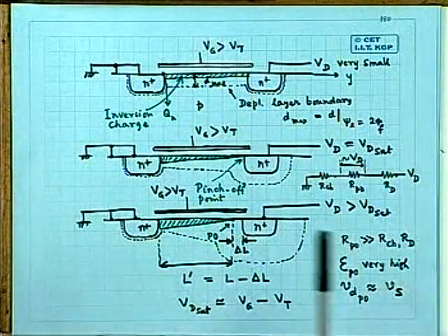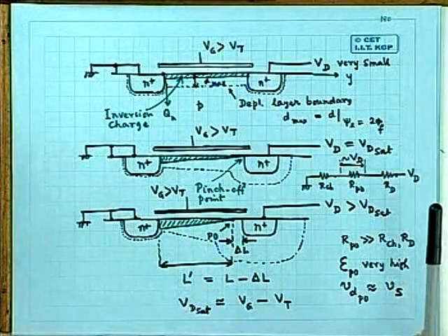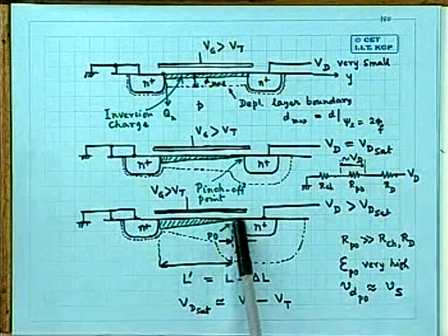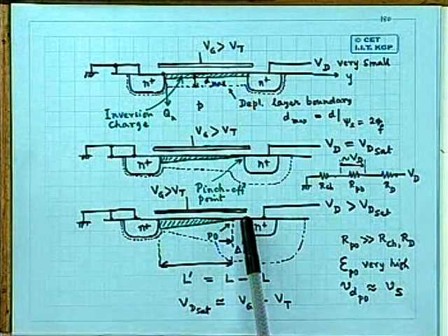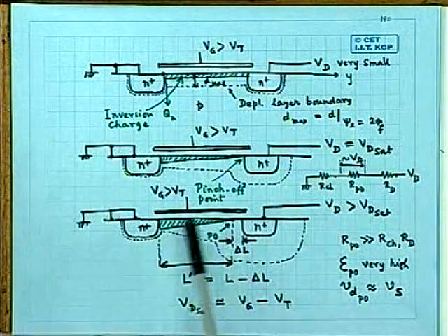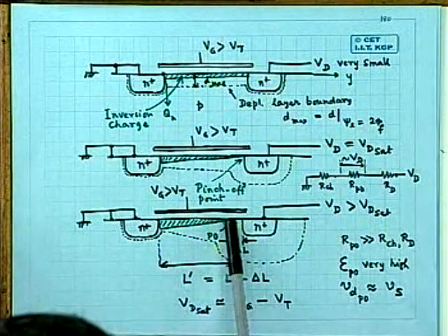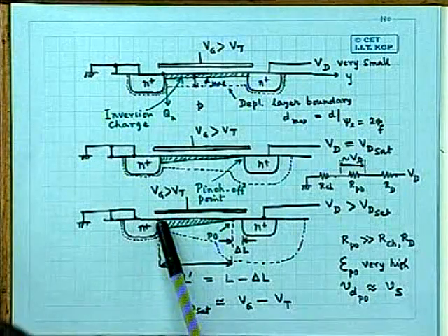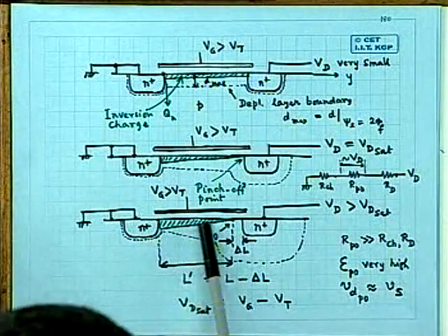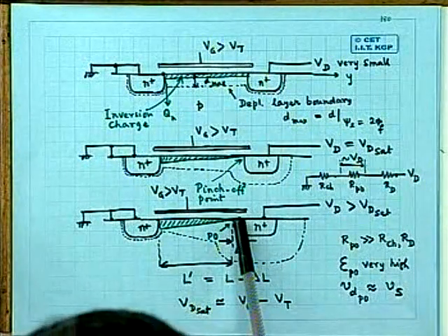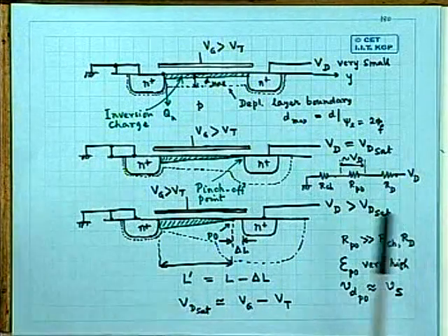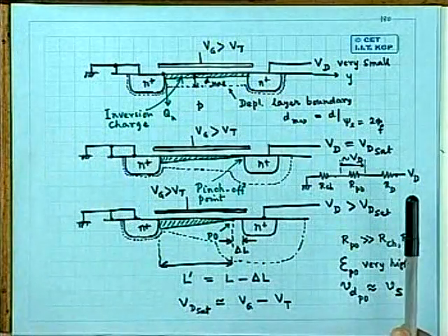As a result, the channel conductance will increase, and hence within this region the carriers will move in saturation velocity. But over this region, the current must be continuous. The current entering here must be continuous. The current which is being sent via the channel and just entering the pinch-off region will be increased because of the reduced length of the channel.